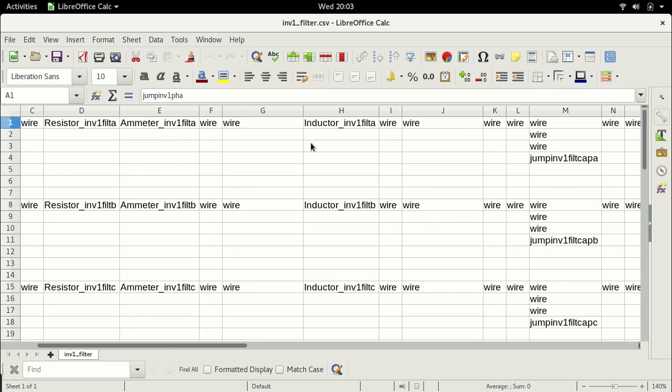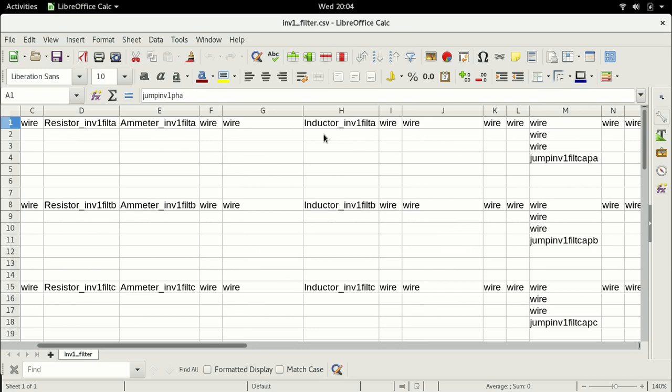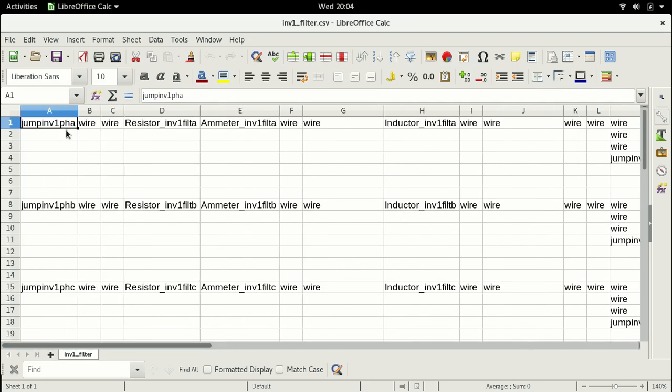Now there are certain advanced control strategies, things like deadbeat control, pole shift control, and certain other things, where they attempt to regulate the voltage across this filter capacitor directly without ever caring what the current through this branch is. But in almost every strategy that you will find, it's a two-stage process. Why? Because when you change the modulation signal, the first thing that will change is the current through this inductor. The current through the inductor changes because the voltage across the bridge changes, and the difference between the voltage across this bridge and the voltage across the capacitor bank decides the current through the inductor.